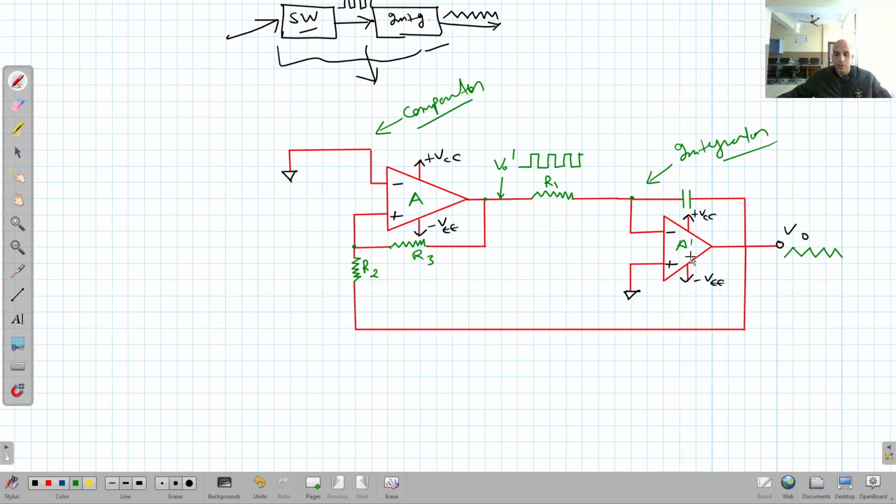Then that circuit will further produce the triangular waves, and these triangular waves are fed back to this input through the resistors R2 and R3. It means the net voltage appearing at this terminal is a combination of two things: one coming from here, and one coming from here. The combination of these two voltages will decide what voltage is appearing here.